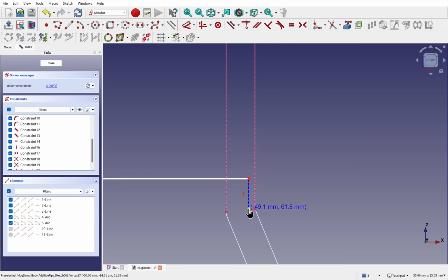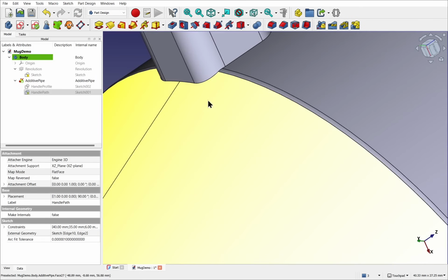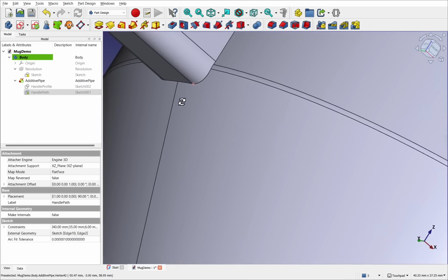And we can decide where this is going to go. I'm very tempted to connect it to this line here, but we have to be careful of exiting out the other side. So I can take this point and place some distance in there if I wanted to, or let's just delete this and connect this point to this one with coincident or point on line constraint. And let's see how this fares. Let's hit close. We can see that we are now embedded within there.